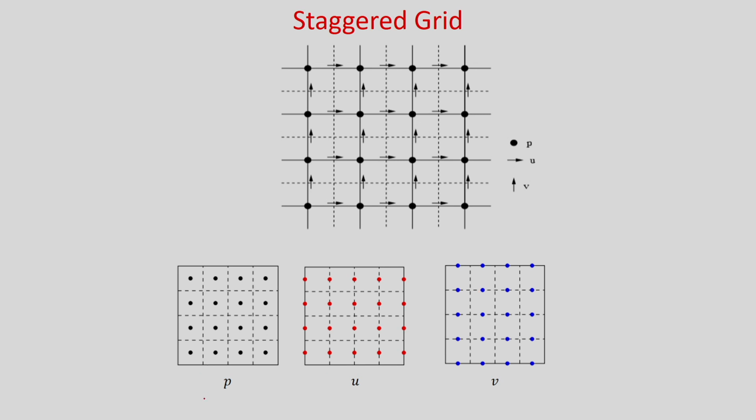But here you can see you have some problem in bookkeeping. For pressure you have interior points 1, 2, 3, 4. Okay. And if you consider the boundary points, then here you have one boundary point, here another boundary point, so you have 5. But when you are considering u, in the x direction how many points are there including the boundary points? 1, 2, 3, 4, 5, and in y direction if you consider the boundary points, 1, 2, 3, 4,